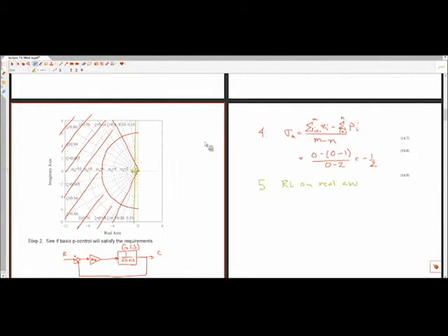So there are plenty of examples where proportional controller works, and also for these specifications, right? If these specifications were such that I didn't care about overshoot so much, this line bends way over here, you would see that there was an area where this peaks in, right? If we were to move this. So that's only for this specific example, which is transfer function and performance criteria. There's plenty of examples where proportional controller will achieve the performance you want.